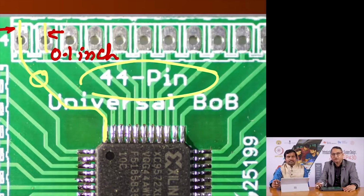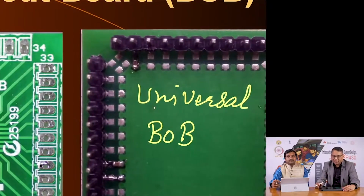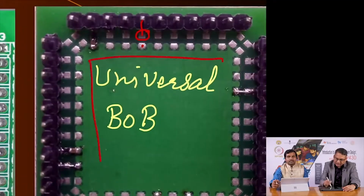Now, the second problem: how do we make this universal? For that we must look underneath. On the other side of this PCB, you see all these pins have two pads. This is a pad connected to this pin, and here is a pad which is connected to what we call the ground plane. That is, this entire green portion is actually copper.